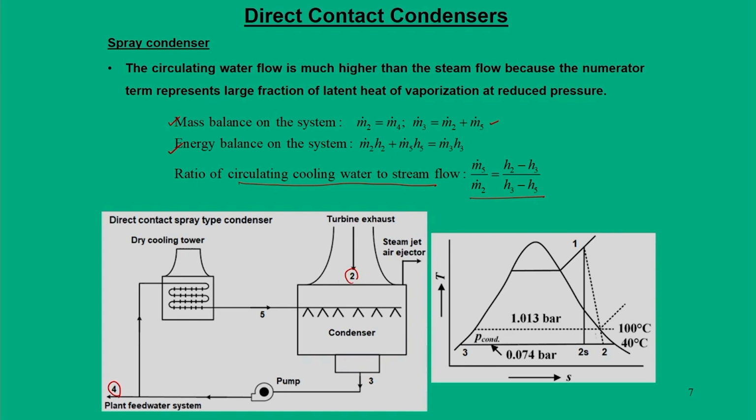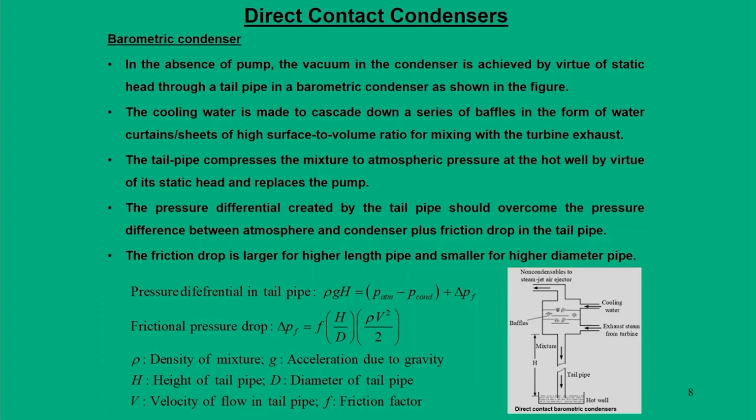This is the most vital part and it decides the load of the condenser. Based on that load, all other parameters like the number of tubes, the number of passes required, and the outer and inner diameter of the tube can be designed.